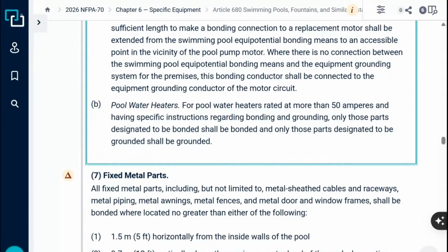Yeah, I think you take the attachments. I think you take your branch circuit to it, and you're going to get an application where you make your connections for your equipment ground. Yep. Done. I think if it's metal outside, you're going to get a lug, and in this situation, it doesn't matter if it's within 5 feet. You're going to extend that connection over from the equipotential bonding grid. You're going to connect over to it. And that's it. Keep them separate and move on. Yep.